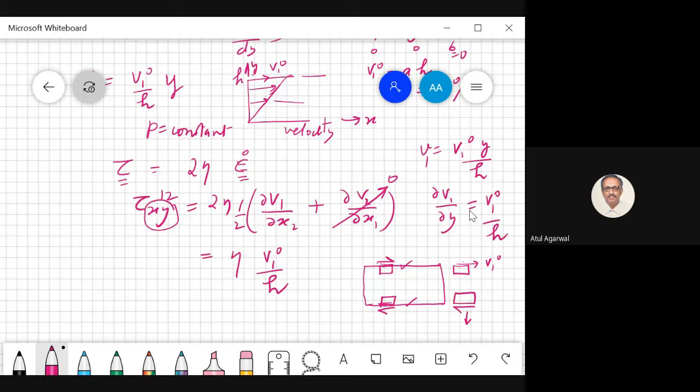So if you take the plate, this is a plate. So what is the force on the plate? This is the force on the fluid. The force on the plate will be like this, equal and opposite. Similarly, this surface. So this was a plate. Now the force on the plate will be, can you see this? So you see the bottom surface was being pulled in the forward direction, while the top surface is suffering drag in the reverse direction.